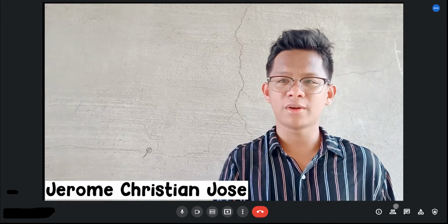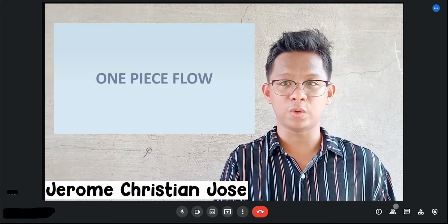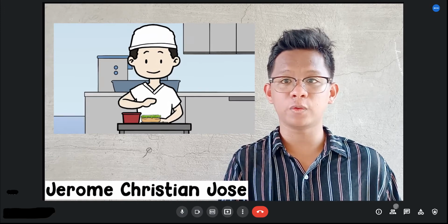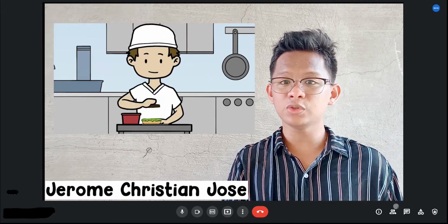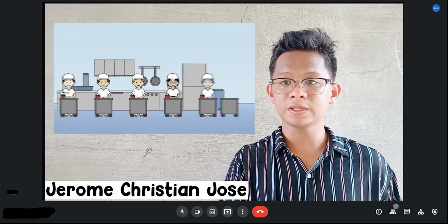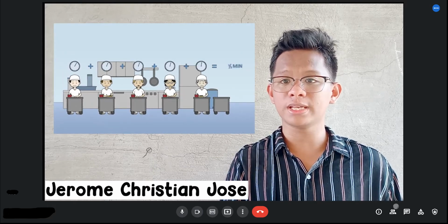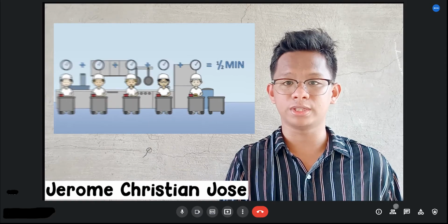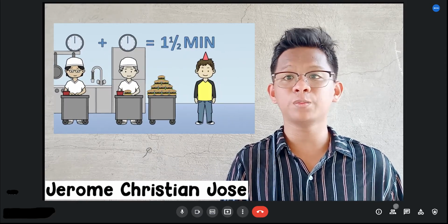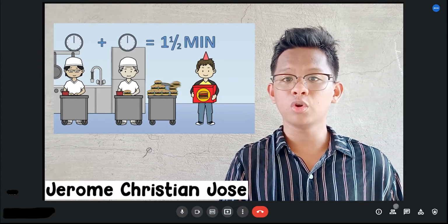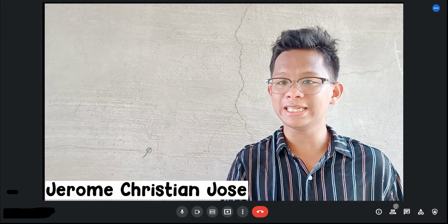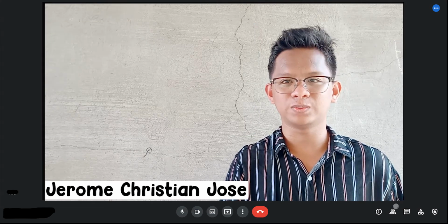Single-piece flow. Cellular manufacturing demands single-piece flow methodology. This is also called one-piece flow or continuous flow manufacturing. This technique is used to manufacture components in a cellular environment. A cell is an area where everything that is needed to process the part is within easy reach, and no part is allowed to go to the next operation until the previous operation has been completed. The goal of one-piece flow is to make one part at a time correctly all the time without lateness.